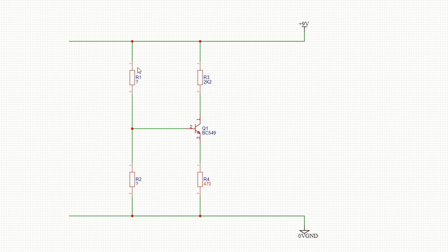And that's where these two come in to set a potential divider, which set the base current with no signal, the base voltage with no signal, which in turn set that voltage, and that from the current through it defines that. So it all goes around in a circle, if you like. It's all interactive. So we want about 1.4 volts from 9 volts. Well, if it's 1.5, it'd be 1/6 of that. So you want just under 1/6, about say 1/7.